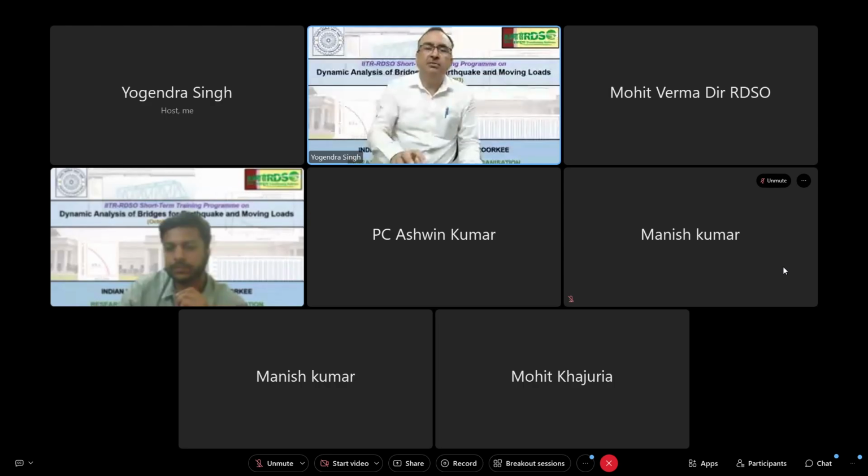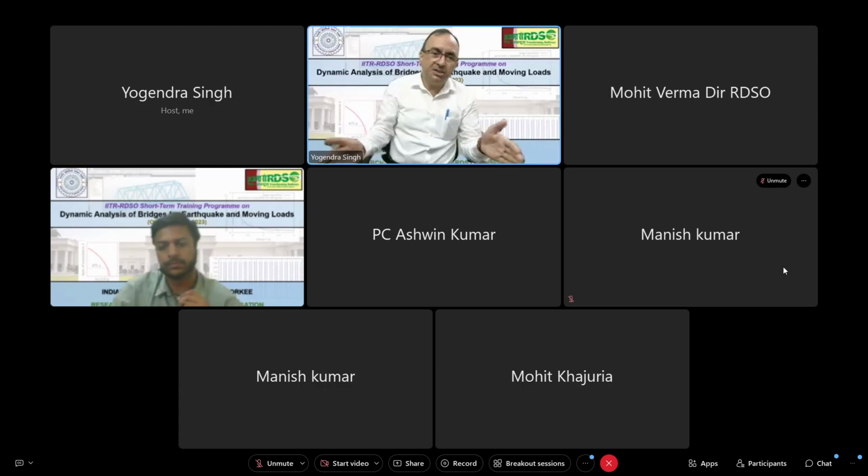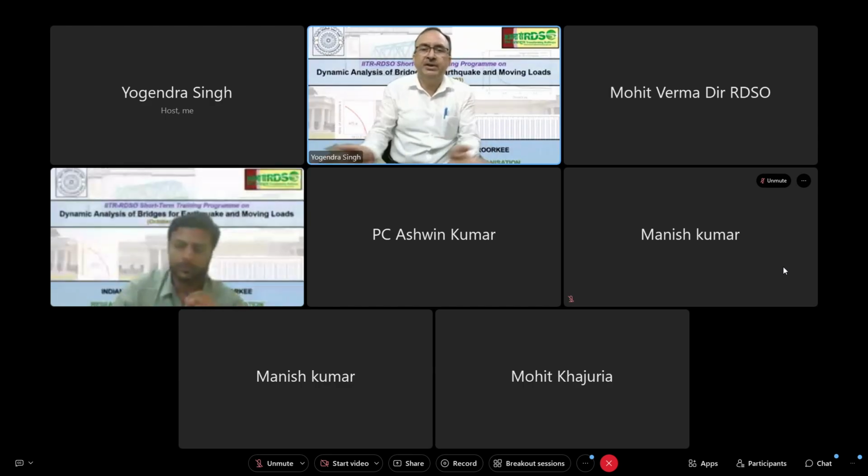So CQC will be used to combine the effect of different modes in a direction. When I perform X direction, I will consider several modes in X direction also. We will use CQC there. Similarly, I will perform the analysis in Y direction, I will use CQC. And then these two can be added by SRSS. And we can see that SRSS is nothing but the square root of the sum of squares of X and Y.